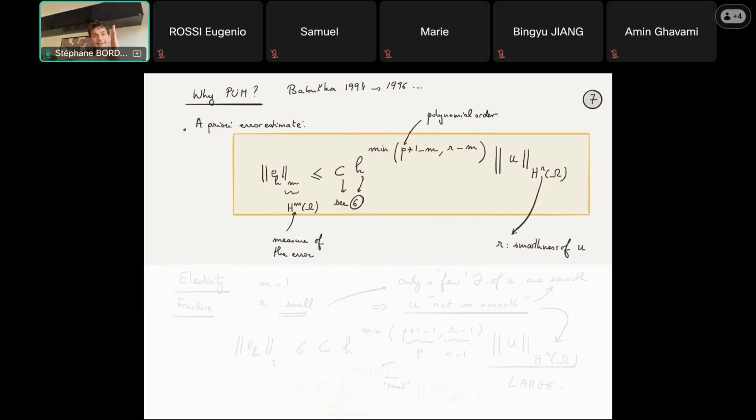In the x-axis, it will have the mesh size or the discretization size, whatever method you're using. Now you will have a slope of that curve, and that will give you the exponent that's here, which you will compare to the theoretical exponent. And you can do that for different values of p, for different values of whatever the parameters of your solution scheme are.